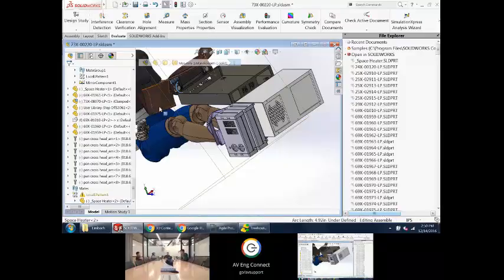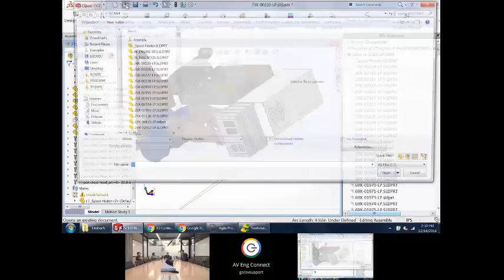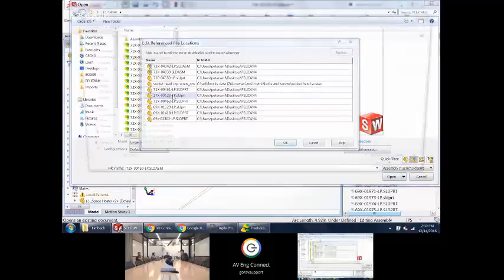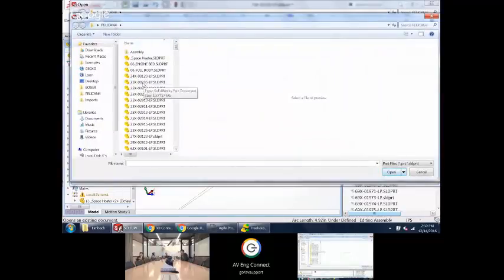You can also swap out stuff when you're doing an open. If you pick an assembly and you hit references, if I double click here, I can swap the reference before I even open the assembly. The trouble is when the assembly opens up, all the mates just go kablamo. So instead of stopping and saying, hey, you broke a mate, could you fix this one?